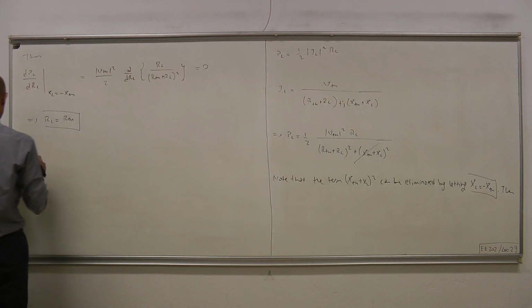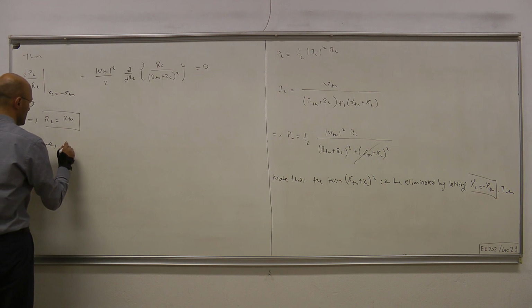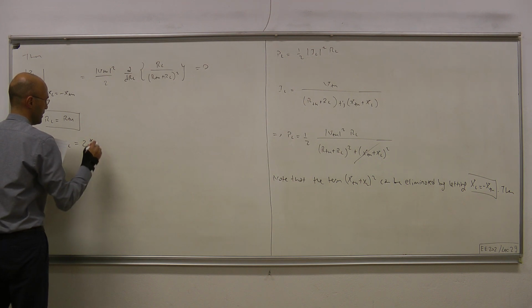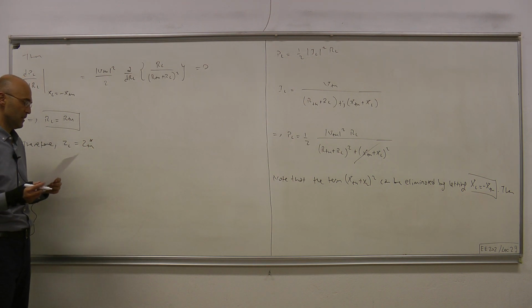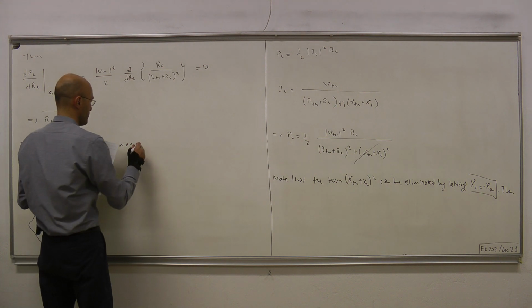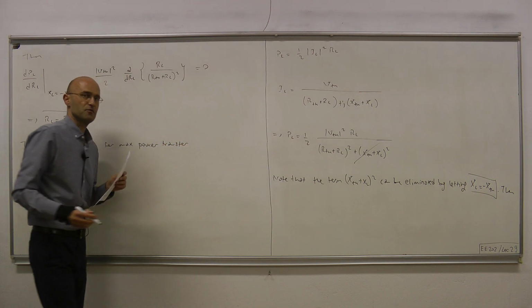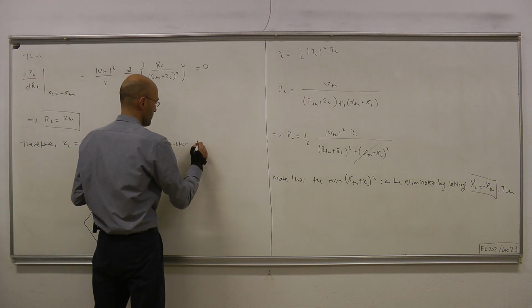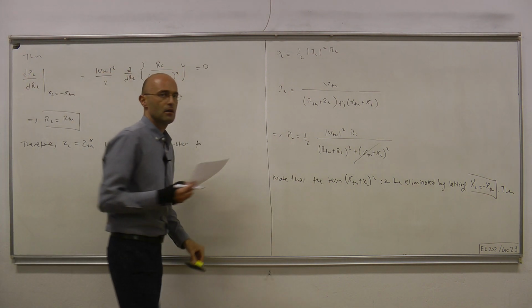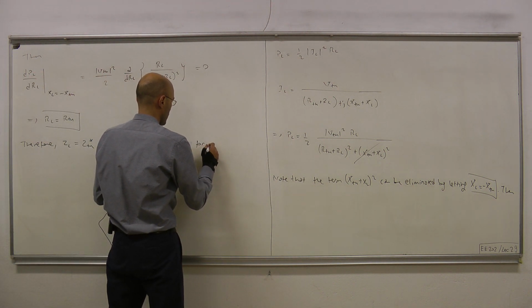So that's a very elegant conclusion. Therefore, load impedance should be chosen to equal the conjugate of the Thevenin impedance for maximum power transfer for our case, where the load impedance is the design parameter. Okay, for our case.